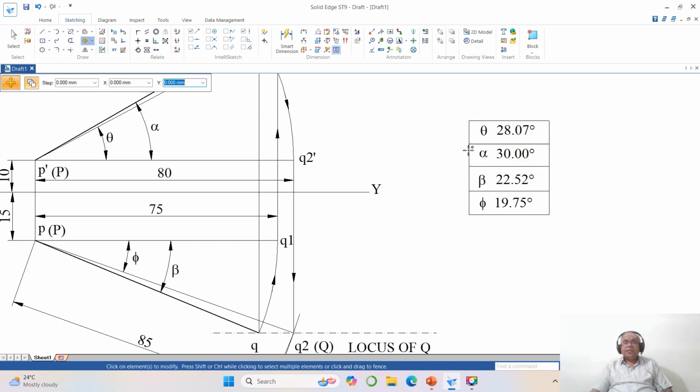Similarly, move, select this line, enter. Go to the move command, click for the point to move from. I don't want the displacement along y direction, it should be 0. So now you just take it and keep it here. Then go to move, select this line, enter.